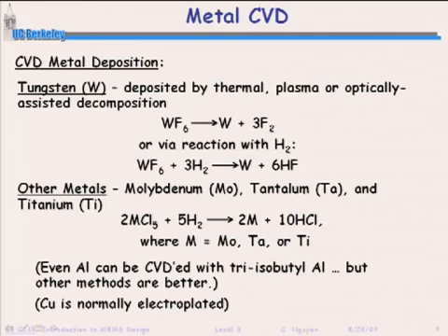Yeah, oh yeah, my group actually did a lot of the early work in putting CVD diamond to use in making mechanical resonators. The reason it makes sense for resonators is that it has a very high acoustic velocity, so it's much easier to get these things to vibrate at gigahertz frequencies.